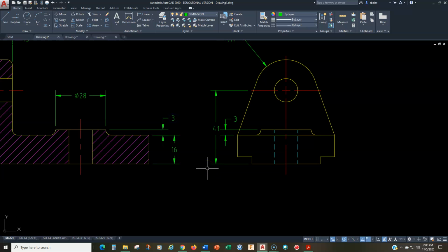In this case, I would want to put the 3 with the 16, right? Not over here, right? Why? Well, because I know the location of this surface from the 16. And then from this surface to the next surface, it builds right on it with the 3. It's right there in line. This 3 is just kind of out there. What's that surface right there? Well, I don't know. Oh, look, I have to look over here. So this is where you want your eye to move as little as possible. So that 3 is not good.